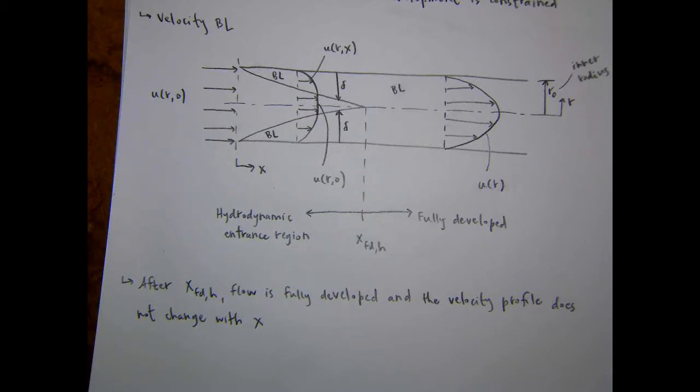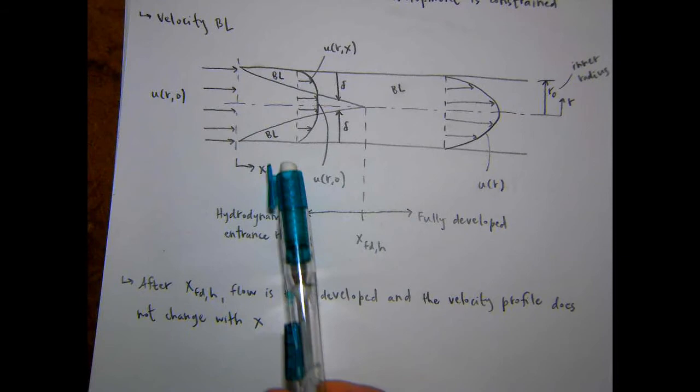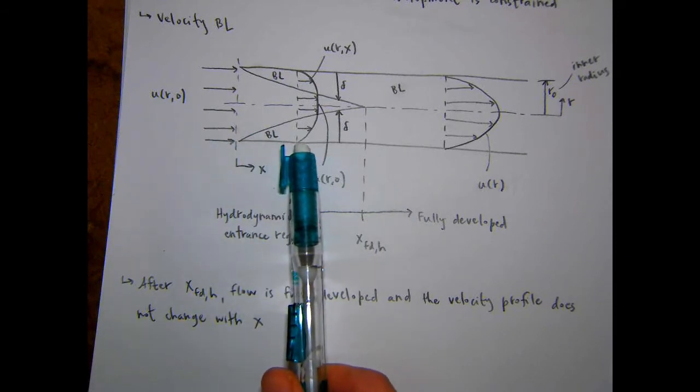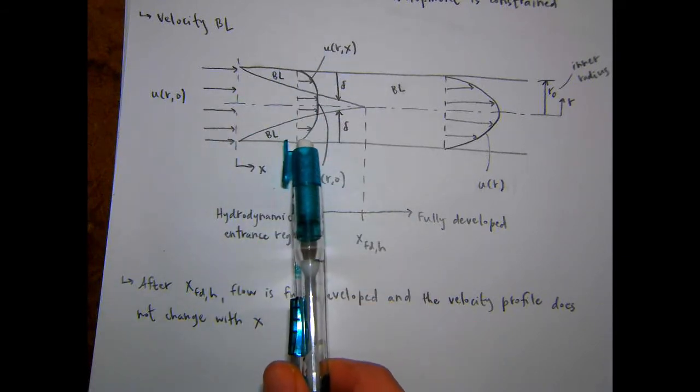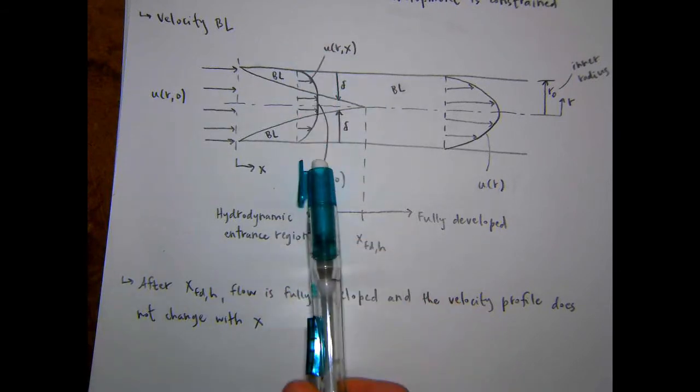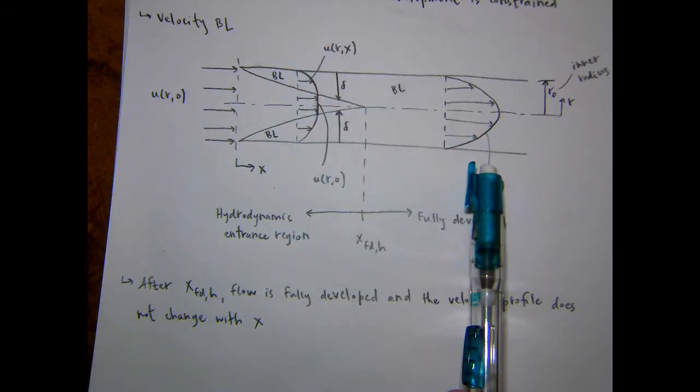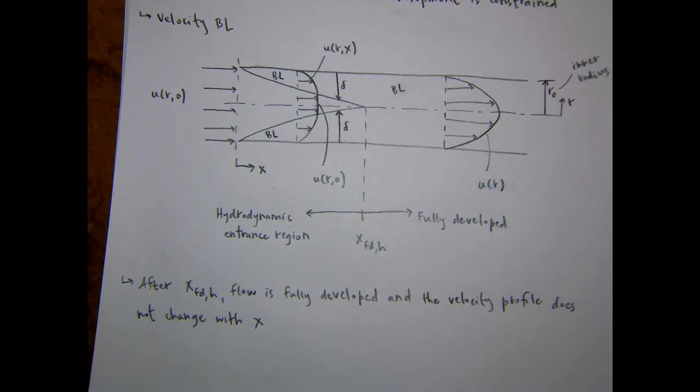Yeah, that's a really good question. So one of the key things, and what we're going to talk about in a little bit, is because the velocity changes over the diameter, you define it as some kind of mean velocity, and that's how you represent it. And it's defined by the fact that m dot is constant, so the mass flow rate is constant.